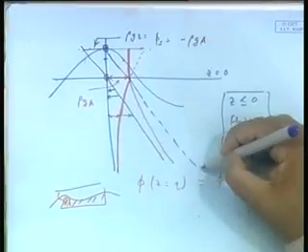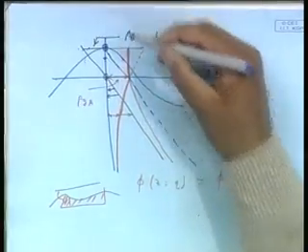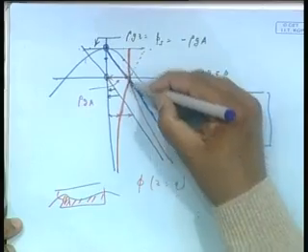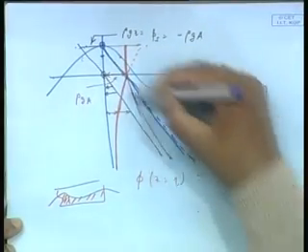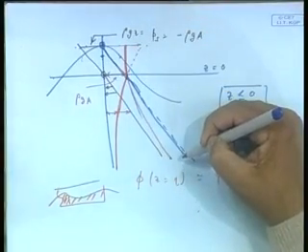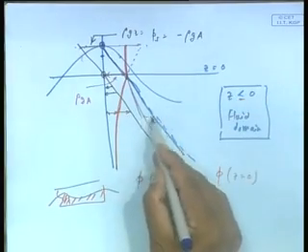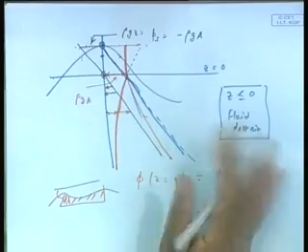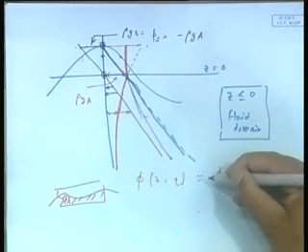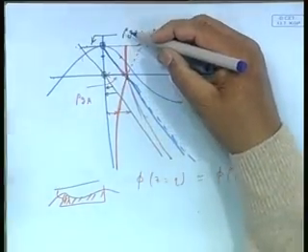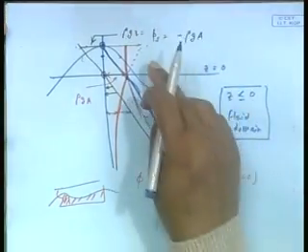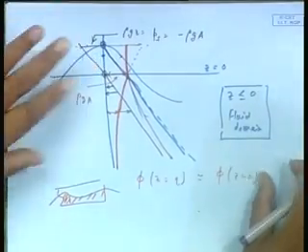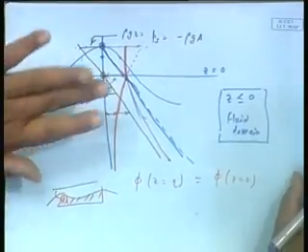Now if I were to see this color, this line is one and reality is this and this. So at least this is not that bad, in the sense that you will not go completely off, you are going to make this much of over prediction, fine, but you do not go completely off. So if you use only hydrostatic pressure, you cannot use rho g z with z equal to 0 as the mean line, you must use an instantaneous water surface. I will give an example of this with respect to a boat in a minute.